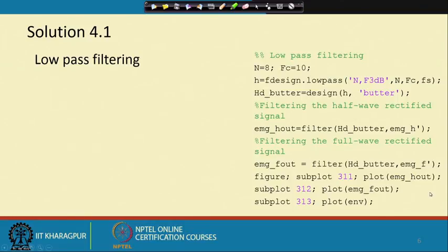After the rectification, we would get a jagged signal, or we can say a lot of ripple is there along with the DC signal. So we would like to remove the ripple, or reduce the amount of ripple, the AC frequencies in that, and for that purpose a low pass filter is suggested with order 8, first starting with a cutoff frequency of 10.